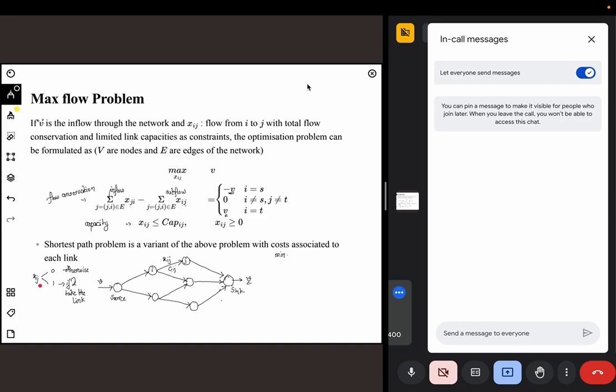So if I use this as my decision variable, I'll try to change this xij so that I minimize my cost function, where the cost function is the summation of whatever cost is associated with that link times whether I'm taking that link or not. So if I take that road, this will be 1 and that cost will be included. If I do not take that road, this will be 0 and that will not be included in my objective function. Now what are the constraints I have?